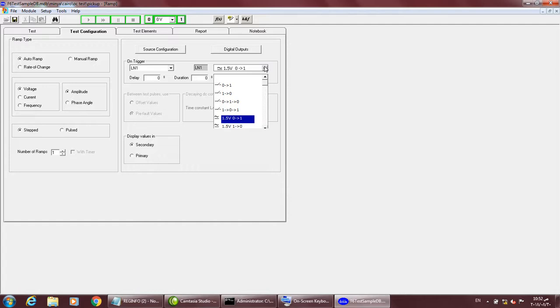I'm not saying it is a limit. Above 1.5 volt, you can use up to 300 volt. That is not limited. This is a lower filter. If you give one volt, then it will not sense it. Similarly, if you select the 15 volt filter and the DC leakage is more, then voltage may appear, say 10 volt. It should not sense falsely. So to filter out we set the threshold. That does not mean the voltage is limited; you can use up to 300 volt. That is not a limit. Okay. So this is the lower duration.